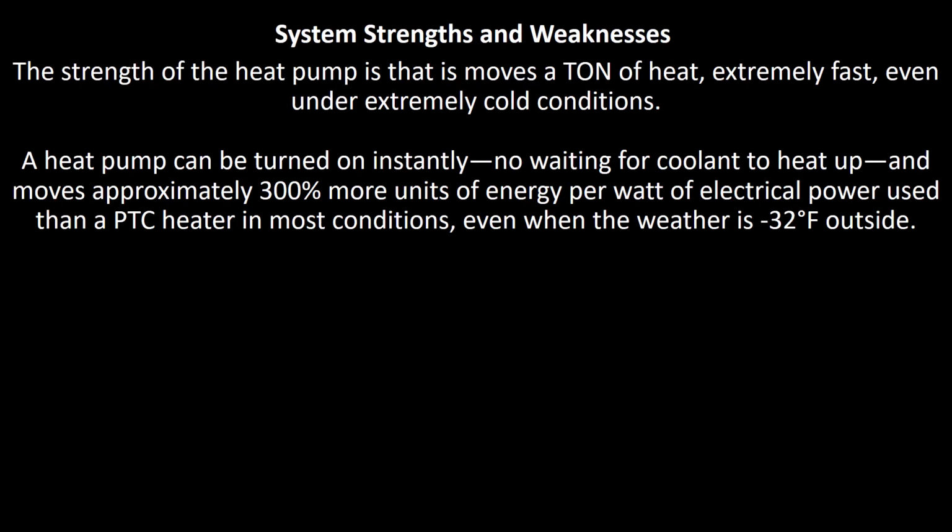The strengths of the heat pump is that it moves a ton of heat extremely fast, even under extremely cold conditions. A heat pump can be turned on instantly, so no waiting for the coolant to heat up. It moves approximately 300% more units of energy per watt of electrical power used than a PTC heater in most conditions, even when it gets to negative 32 degrees Fahrenheit outside. Put in layman's terms, a heat pump is 300% more efficient than a comparable PTC heater.